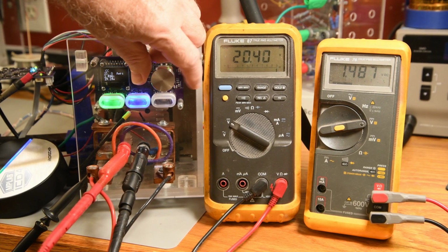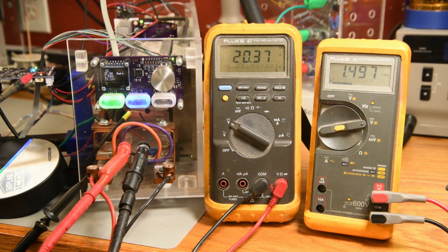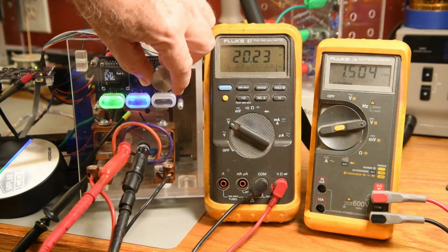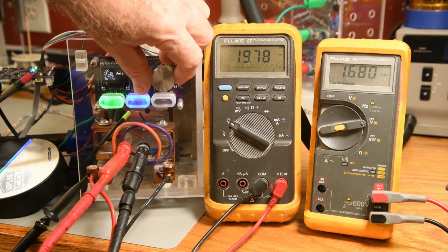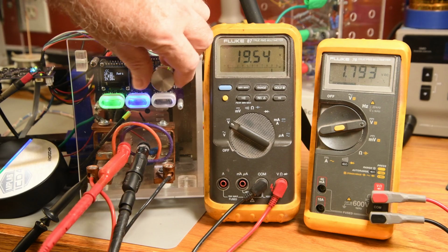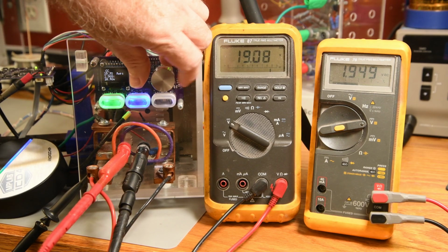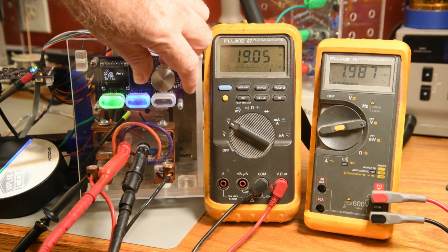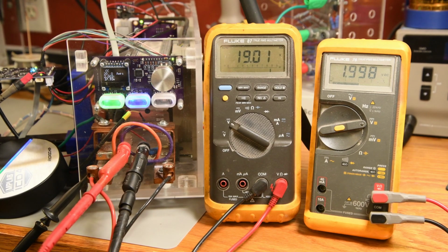At 15 amps, everything seems to be okay, and I'm right at a 300 watt load. I'm shooting for a load that can handle 600 watts, so really only at half power right now. I'll take it up to 20 amps. My voltage readout on the load is bouncing around quite a bit. If I remember right, I'm updating the display 5 times a second, maybe 4. I've changed it a few times.